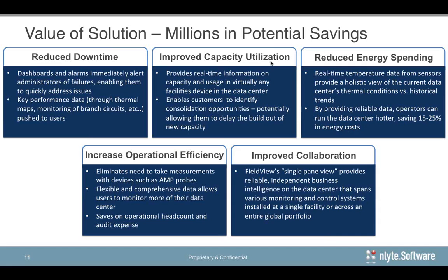An example of that would be our teaming, which is the proactive warning that I mentioned just a slide ago, making sure that the B side, whether that be a circuit or another PDU or generator, will capture the A side should there be a failure. And that teaming concept is built within the application, and it's proactive, making sure that B is backing up A all the time.